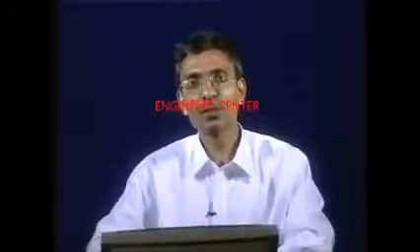Obviously what happens is there will be a large amount of friction, and because of the friction the pressure drops. That means there will be an expansion, the pressure drops from the inlet pressure to an exit pressure. So this is an example of a throttling process. A throttling process also takes place when you are forcing the fluid through a narrow tube, for example a capillary tube in a vapor compression refrigeration system.